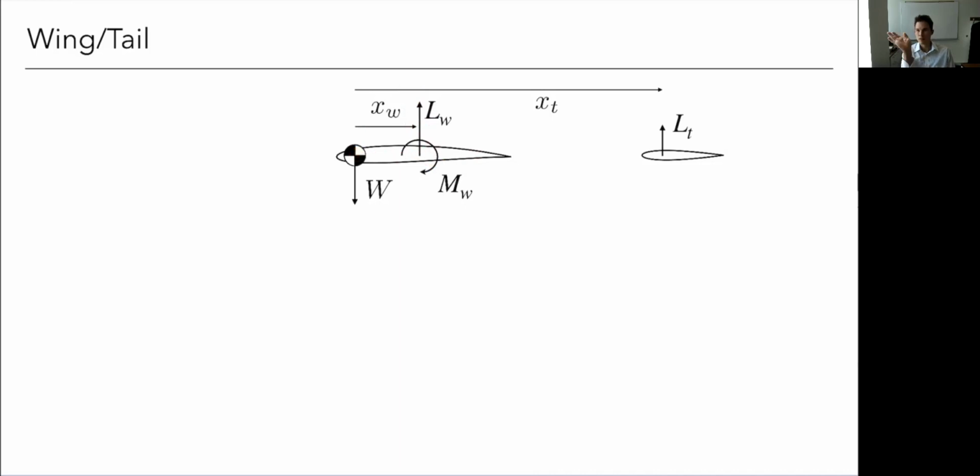Okay, so for this discussion, let's just say it's behind here. That lift, if we do R cross F, is also creating a nose down moment. So both of these are going to cause my airplane to nose down. So if I had this lifting surface back here, a tail, I need to create a moment in the opposite direction, a positive moment. And to do that, if we look at the direction, R cross F, I actually need my tail to lift down. So this LT is going to be negative. I need to generate a negative force at the tail.